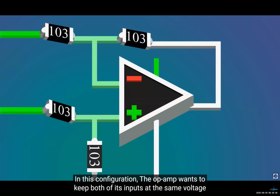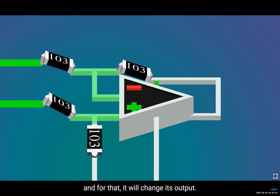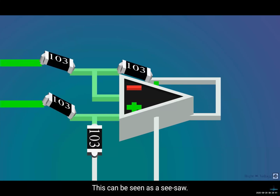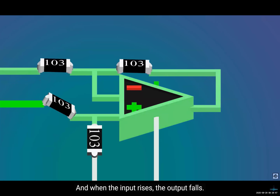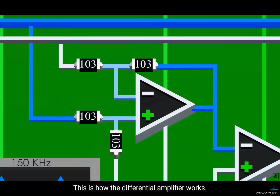In this configuration, the op-amp wants to keep both of its inputs at the same voltage, and for that, it will change its output. As the feedback is to the negative input, the output varies according to the voltage at the negative input. This can be seen as a seesaw. When the input voltage falls, the output rises. And when the input rises, the output falls. This is how the differential amplifier works.